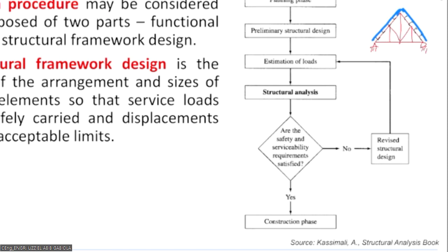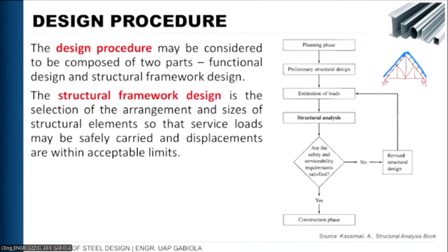So that may be the cause of your failure in your checking. Upon verification, you have reduced your live load, so eventually your shear, your moment, or your forces will reduce also. And then upon rechecking for the required checking based from the code, you will see that your component will now pass all the requirements. And then eventually we will proceed to the construction phase of the project.